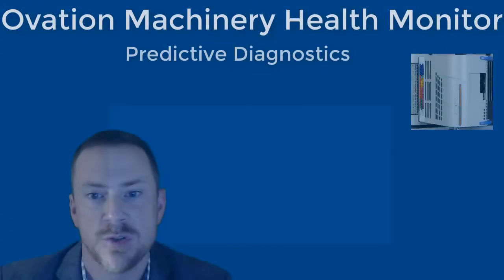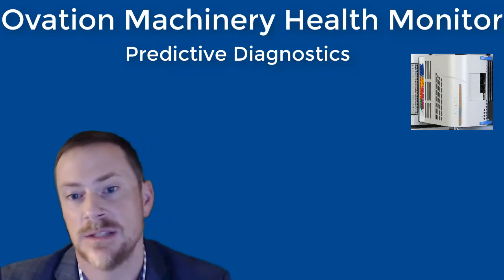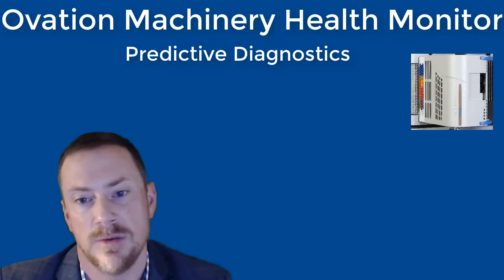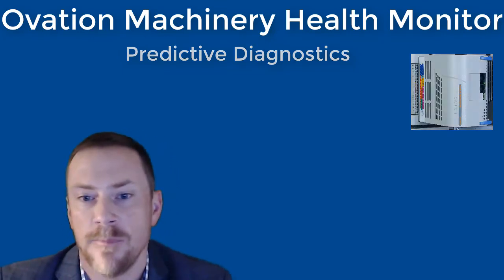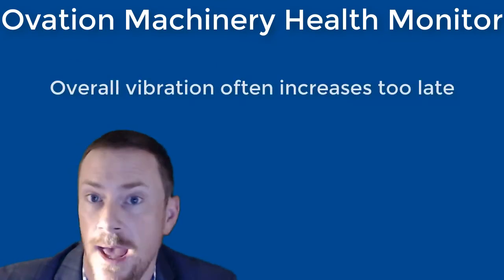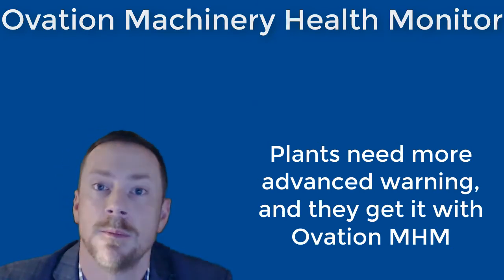Now, we've been trained by the OEMs and the API standards to believe that the overall vibration value is the best piece of information that we have regarding equipment health, and that we can simply rely on that overall value to keep us from damaging our equipment. That's really not the case. The protection system is designed to avoid catastrophic failure, and in most cases it does do that, but not in every case, and it almost never gives us advanced warning of developing problems.